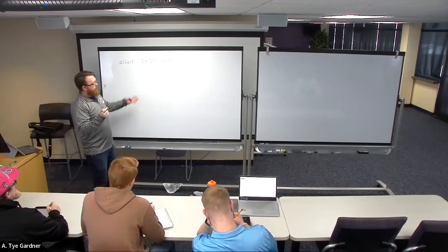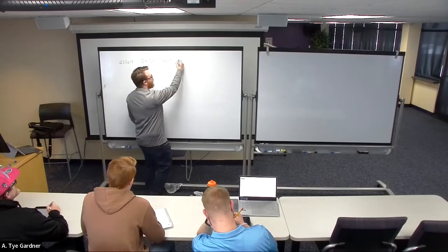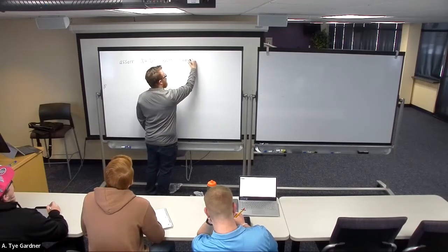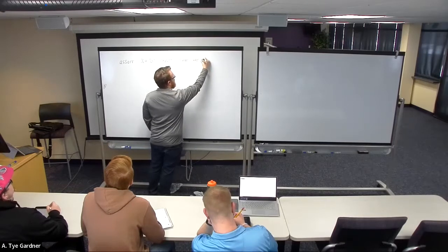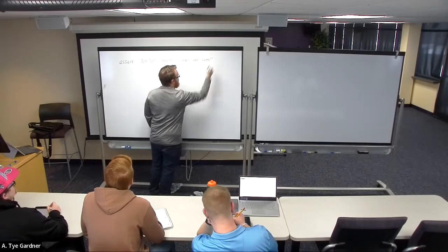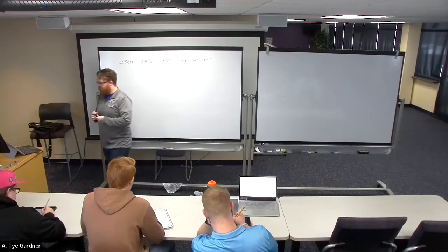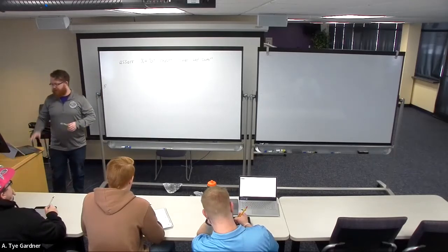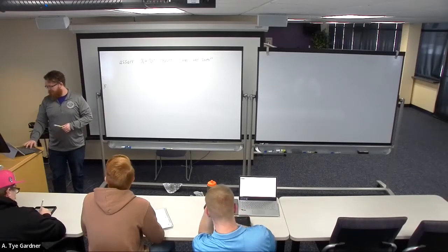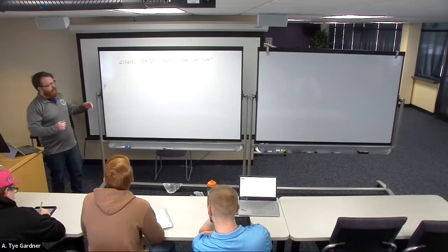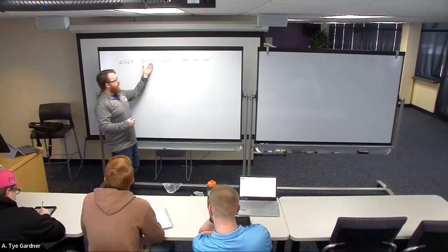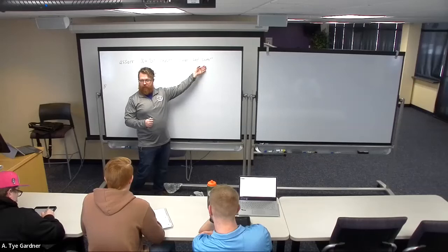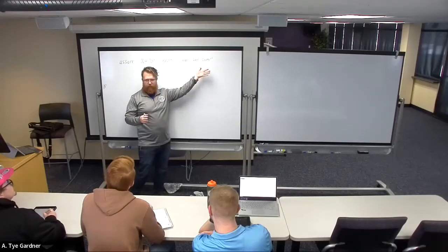So you could say something like error, bad sum. That's the example that it actually uses inside of the test bench that I've provided for you. And all that's saying is that, whatever test I ran, I was expecting a 0 to be on x. If I didn't get it, let's print to the TCL console that there was a bad sum.